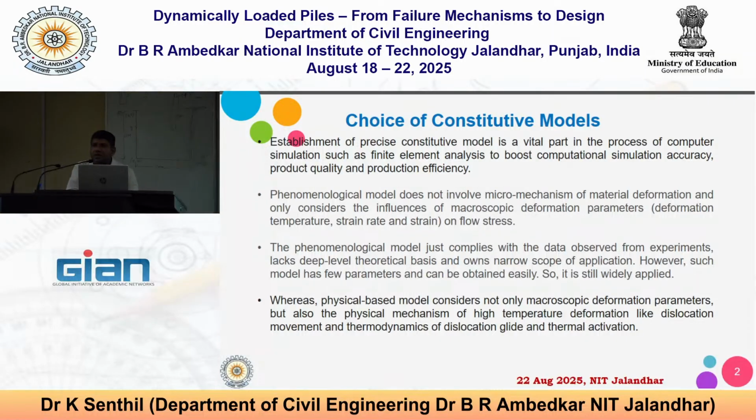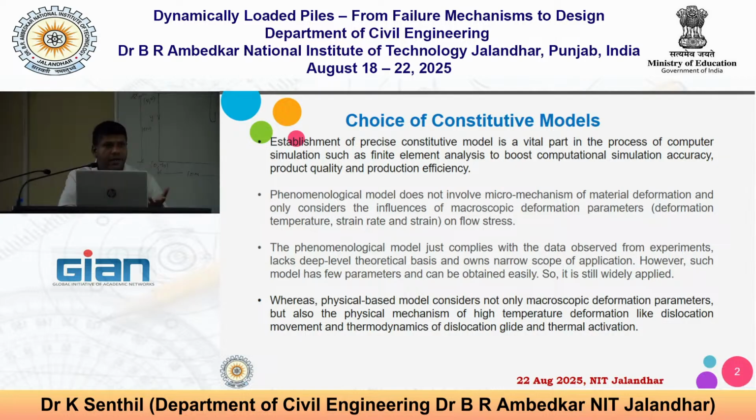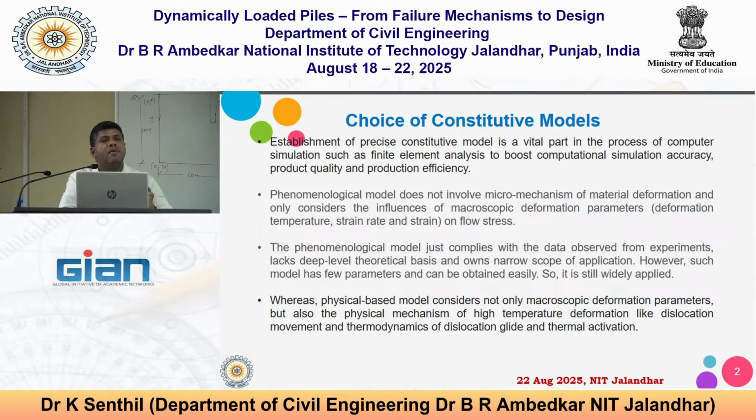This is a simple constitutive model. Now, whatever you want to add, you can add. So you couple it and your material model will be strengthened by adding whatever: the strain rate, stress rate, state of stress, triaxiality, temperature, right? So you can improve the models. There are generally two different models: phenomenological models as well as physical-based models.